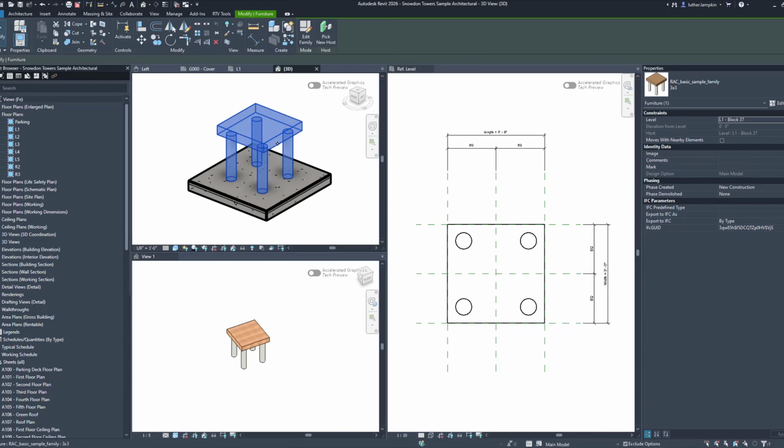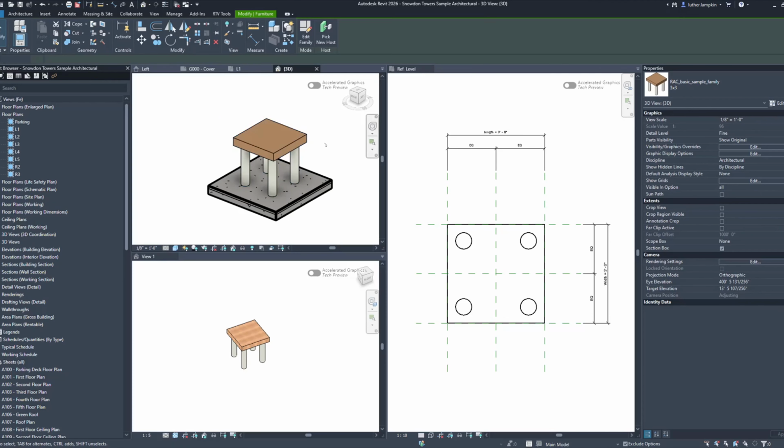Or with this, I can go ahead and say, hey, I don't want parameters tied to anything. I just want a height parameter that I can modify inside the project. So I wouldn't make any of these tied parameters to be presets. I would just do one with parameters saying height, length, and width, and then I can control that in the project and I can copy it multiple times. So you really have to determine what type of family you're trying to create, what the purpose is, and how you want to do it.